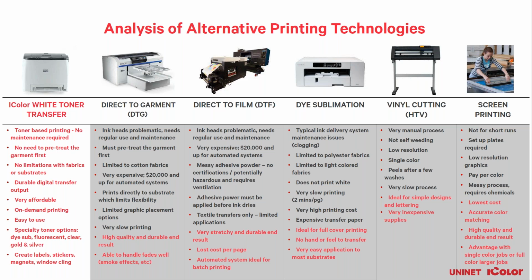When you talk about DTG and DTF, they're very similar in the way that they operate, and they're both ink-based systems. Ink heads must have regular use and maintenance, or you're going to have problems. You have to do a nozzle check probably every day. You want to use these machines every day to every other day. Otherwise, they can clog and lead to other issues. So it's something that you have to really think about if you're going to dive into DTG or DTF. Do you want to be dealing with the maintenance? Some people say yes, and there are pros there, and some people say no, I don't want to deal with it. I might be an occasional user, and that's where white toner might be better.